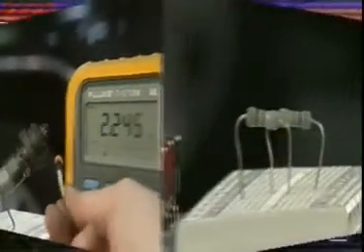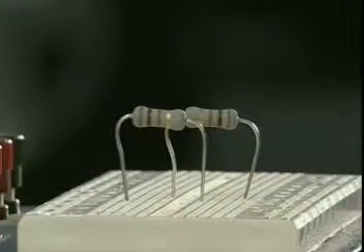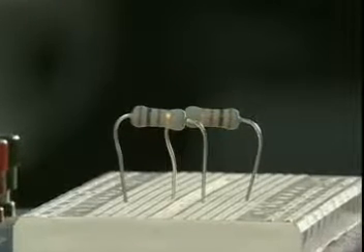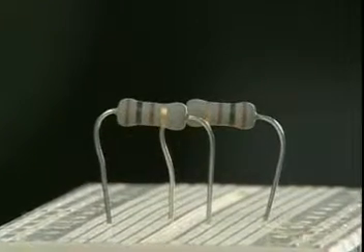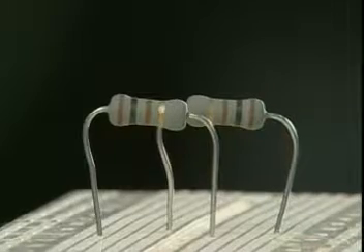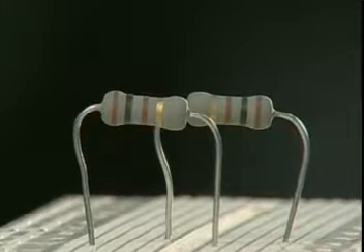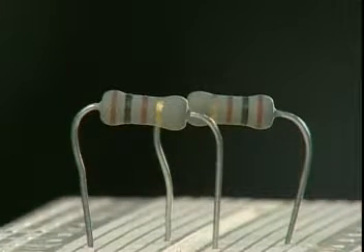Other components are designed to cause variations in resistance that change the current or electrical pressure in that part of the circuit. These common carbon-type resistors, for example, are rated by differences in their resistance. The color bands around the resistor's outer diameter indicate resistance. The color code can be compared to a chart to determine the exact resistance.